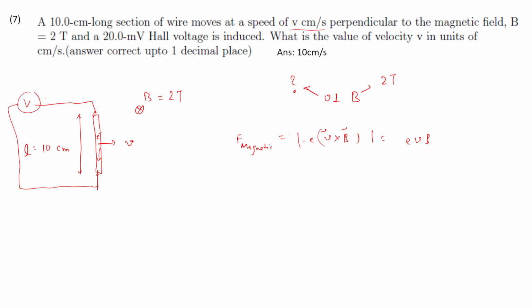Okay, and this reading will be related to the field developed inside it, due to this separation of these charges. So that will be equal to the electric field E times e, or that we call the Hall field, and it will be equal to V by L, where L is the length, or this is just nothing but your EMF, electromotive force.